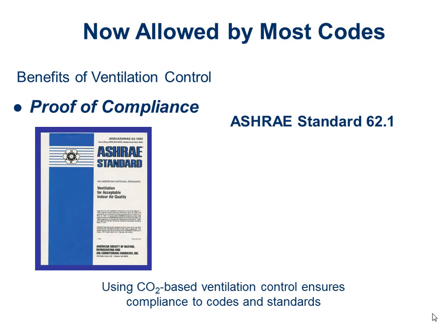So ASHRAE 62.1, as we mentioned, is derived based on CO2 levels to get the ventilation rates, and it also does allow dynamic reset, dynamic changing of the ventilation air to match the CO2 levels that we're trying to achieve.